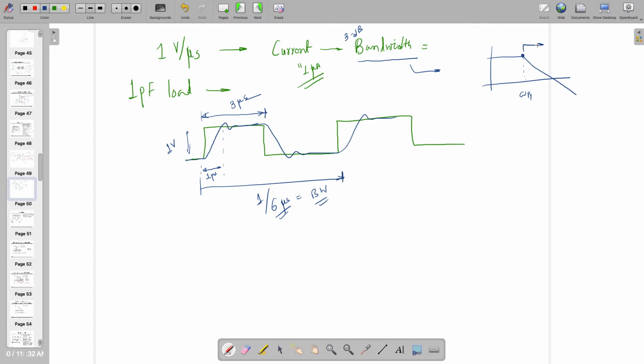We can add, look, adding a zero. I'm saying how to design it without adding any transistor or anything. How can you do that without adding any transistor? Maybe you can tune it, W by L and all these things are allowed. Reduce the capacitance. So how to reduce it? Okay.